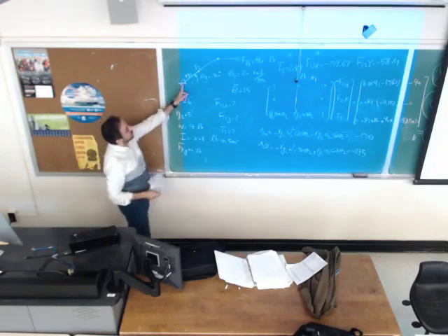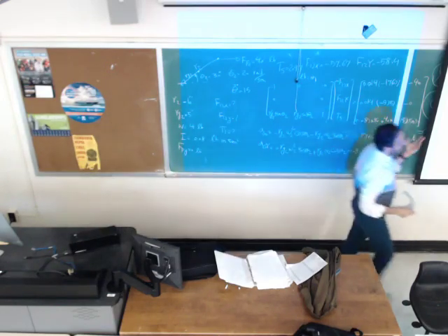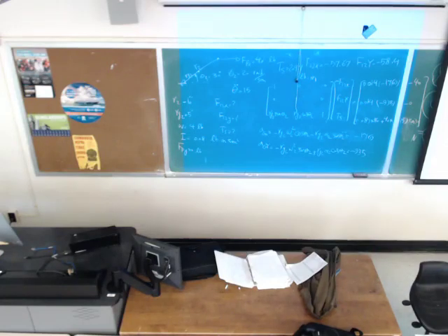Because the reaction of that force is applied to the ground, we would like to know how much force is going to be transmitted to the ground. It's going to be F21. The magnitude is going to be the same, but the direction of the force will be opposite. Action and reaction in Newton's law. F12x changes to F21x, and F12y changes to F21y. But the magnitude will be the same, because a negative sign squared is going to be positive. So the shaking force is going to be 59.22 pounds.